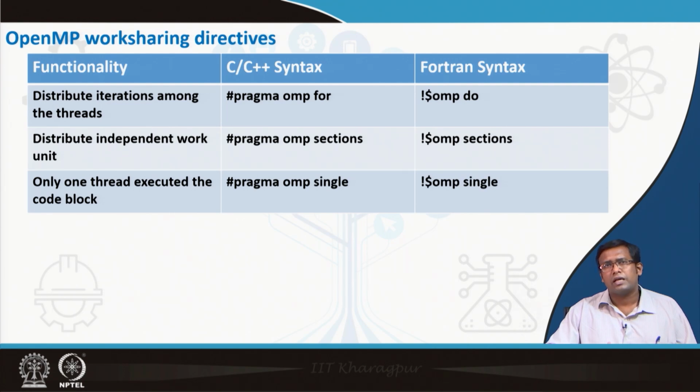And then there can be another work sharing case. Again we are discussing solving the momentum equation in the x, y and z directions, and in a certain case we see that there is no force, therefore no acceleration in the y and z directions, and we only need to calculate for the x direction. So, we will not launch any thread in the y and z directions.